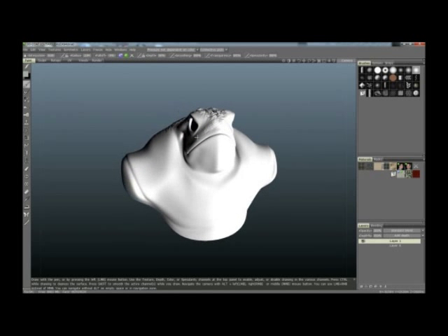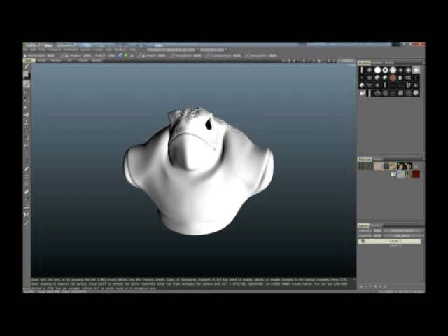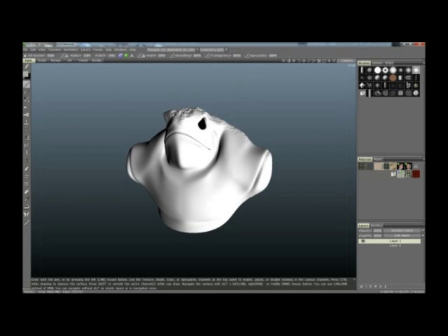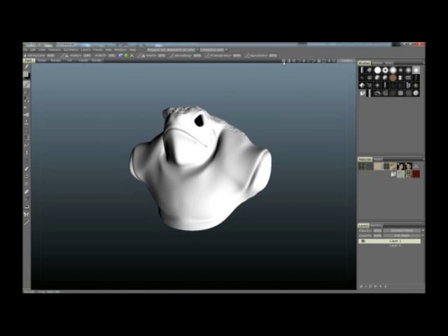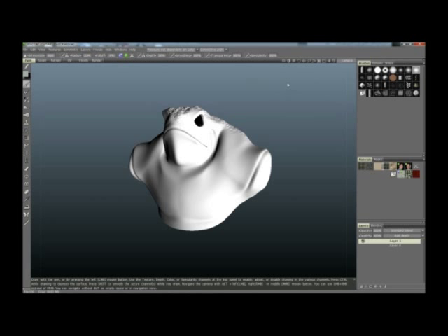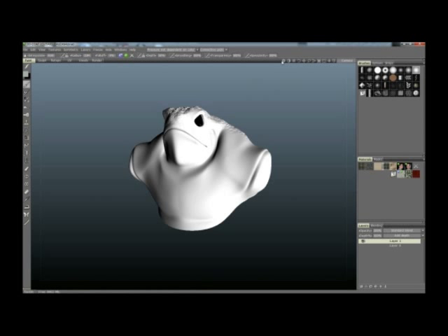The other thing we want to get rid of is this hard lighting on one side of the object. If you go and look at the top right hand of your box, you'll see that there's a little taskbar that has a few icons. We want the first three. The first one there is going to be your ambient light. So you want to set that to around 60, just to even out the light over the object.